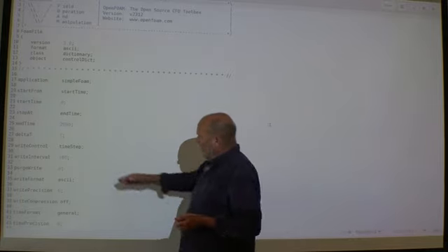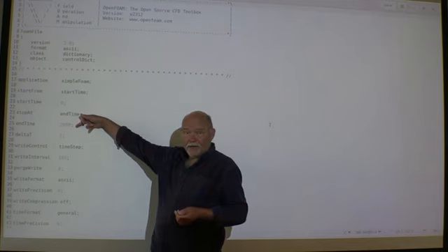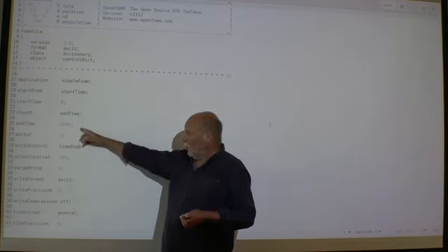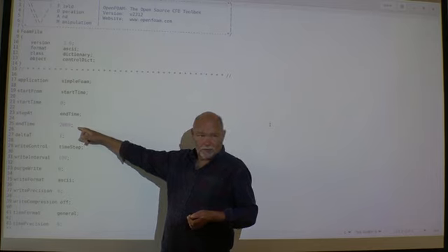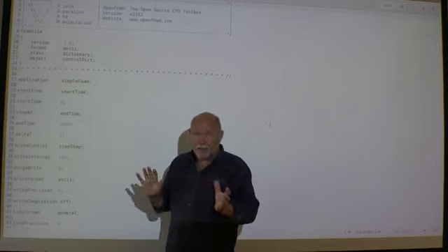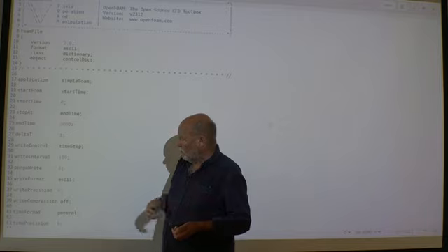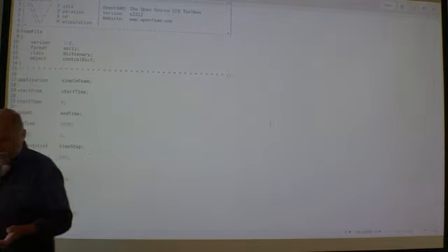So the idea is you put a big number for end time, and then you start the program. It will automatically stop when it has found a solution, hopefully before it reaches 2000. If it reaches 2000, then something may be wrong, or maybe you have to increase the number. So that is a steady state setup for you.